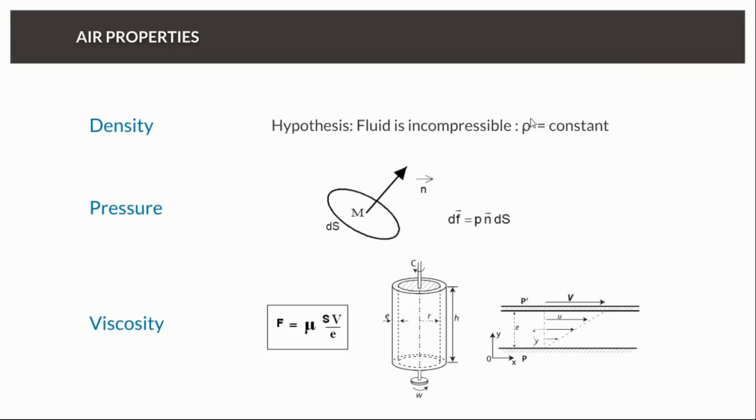It's, as I said, in most of the cases, because people will work in, for instance, Formula 3, where there'll be some air restrictors for the engine, then the flow can get sonic, and the Mach number will increase close to Mach 1 and reach Mach 1 at the throat at maximum flow rate. But globally, for the rest of the external aerodynamics, we can consider the fluid as incompressible.